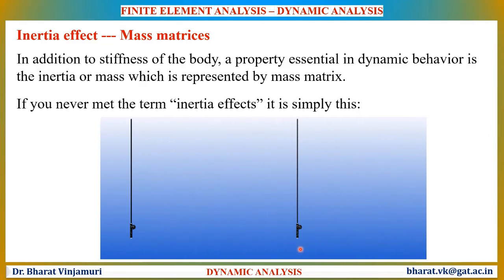But on the right, the rotation is applied at a faster pace, which is known as dynamic analysis. Notice that at the beginning, the handle moves before the tip realizes that there is a movement to be made. Then the tip tries to catch up and the structure begins to shake. Note how the rod vibrates even after the rotation is done. Such an effect can be understood only with the effect of inertia.